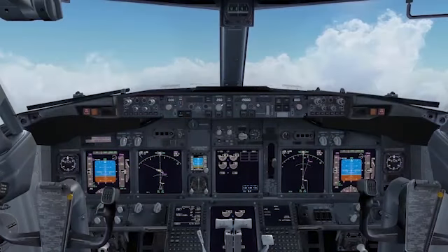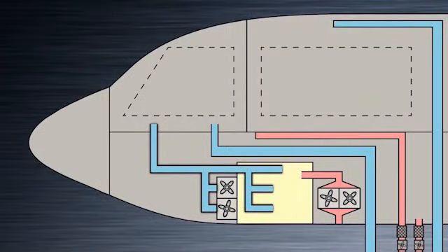Because these systems are important, for example to present data on the flight crew's display units, they must be kept cool and free from the risk of overheating. For this purpose, the air conditioning system also has an equipment cooling system designed to remove heat from the electronic components near both the flight deck and the electronic equipment bay located slightly aft and under the flight deck section.